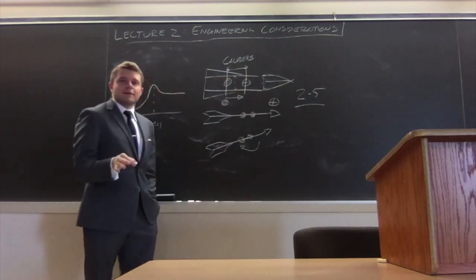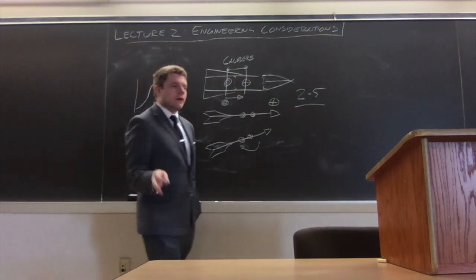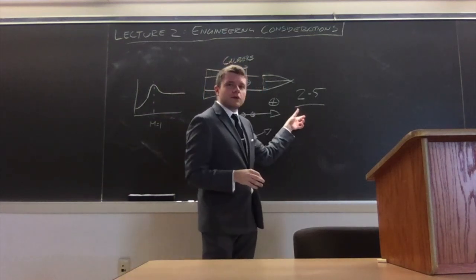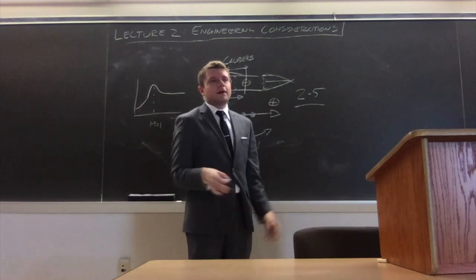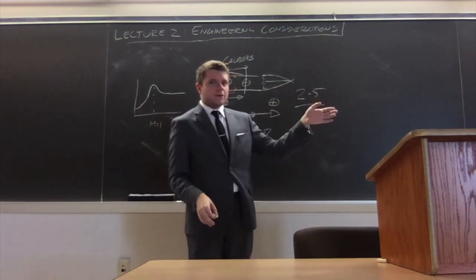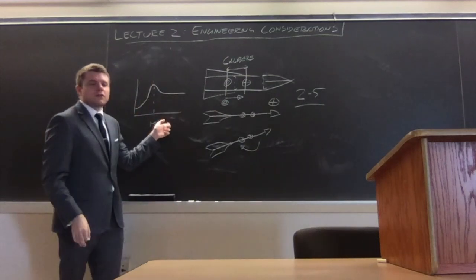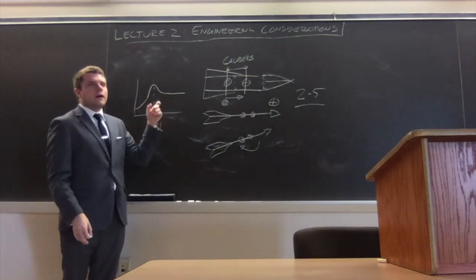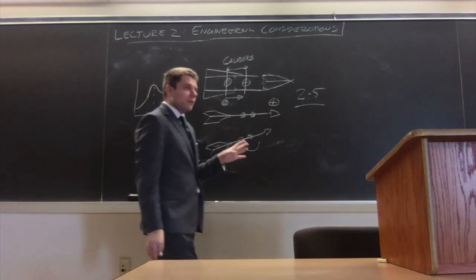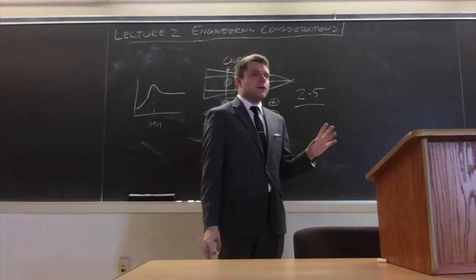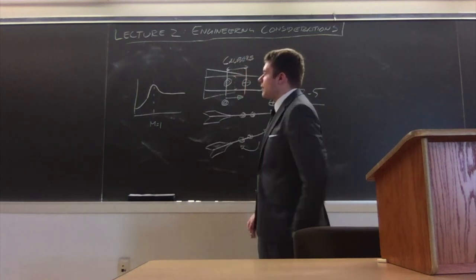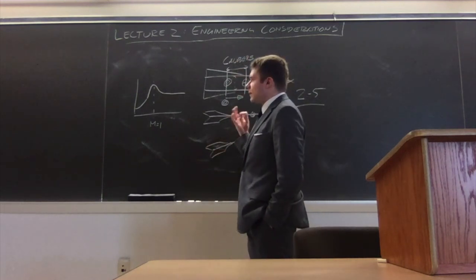And what this means is that if you're flying a rocket, you work really hard to get this thing perfectly stable. You get it within 2 calibers of stability. You've got this nice, long, thin rocket. You're going to say, all right, I'm going to go break the sound barrier. It launches, passes through the sound barrier, goes transonic, goes completely unstable and out of control. This is a problem that plagued aerodynamic people for years when we were trying to send a human supersonic, and it's something that rocketeers deal with as a problem because it's not immediately intuitive.